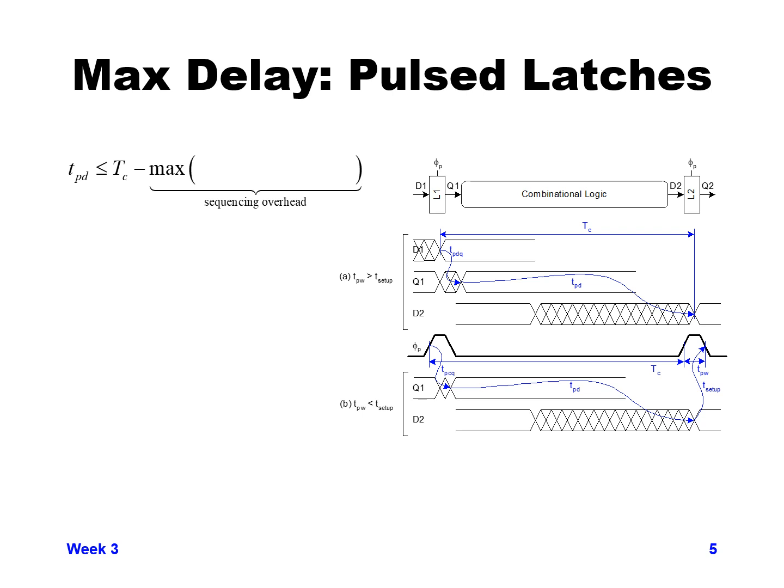Now, if our pulse width is long enough such that the pulse width of the clock is larger than our setup time, then we get the situation shown in row A, where our data can come in after the clock edge rises, and just flow transparently through the latch before it closes for latch L1. And so in that case, we get a propagation delay from data input to Q output, so TPDQ, D to Q.